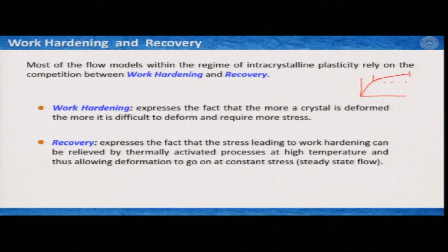However, recovery is essentially the opposite process of work hardening, which expresses the fact that the stress leading to work hardening can be relieved by thermally activated processes at high temperature, thus allowing the deformation to go on at constant stress, which is also known as steady state flow.